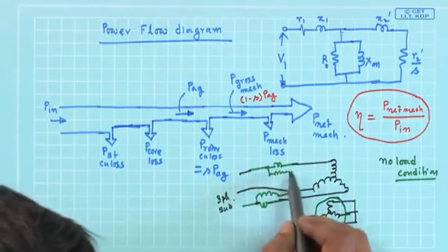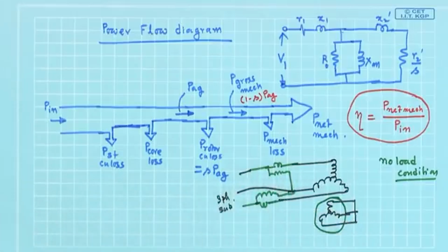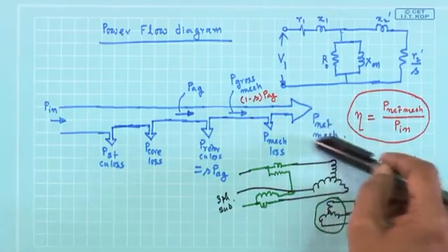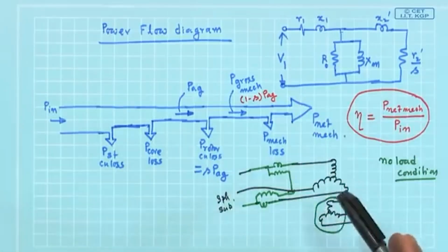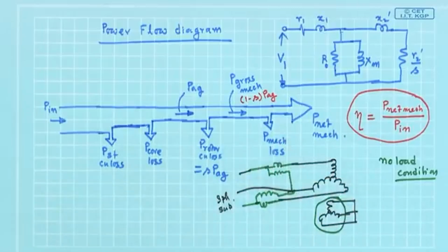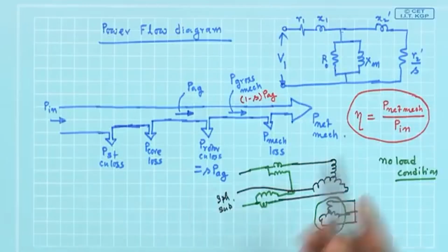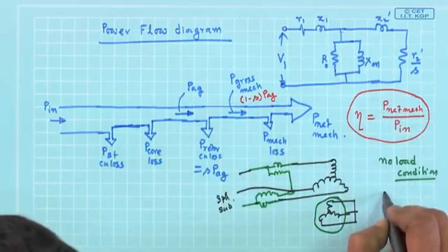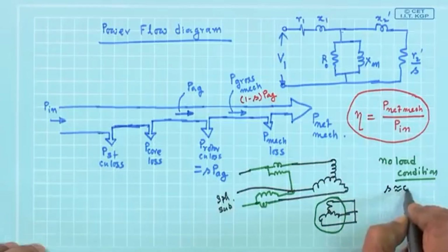And the wattmeter is going to read then what? So, this part is not there, and then slip has to balance only the little bit of frictional torque present. Therefore, slip will be very small, and it will run very close to synchronous speed. If that runs, people say under no load condition slip is practically 0.